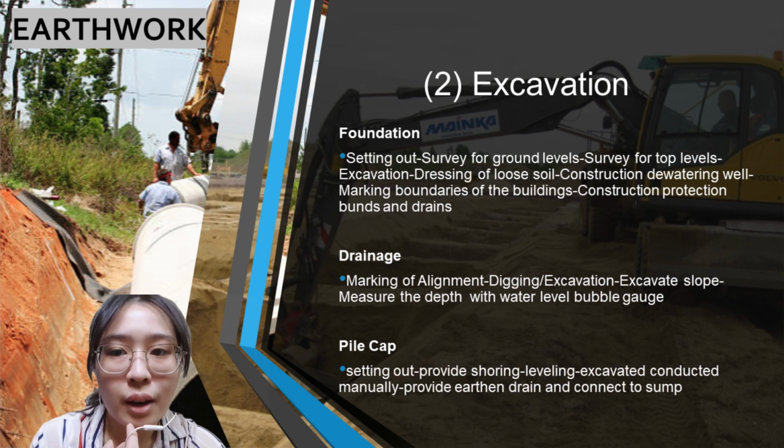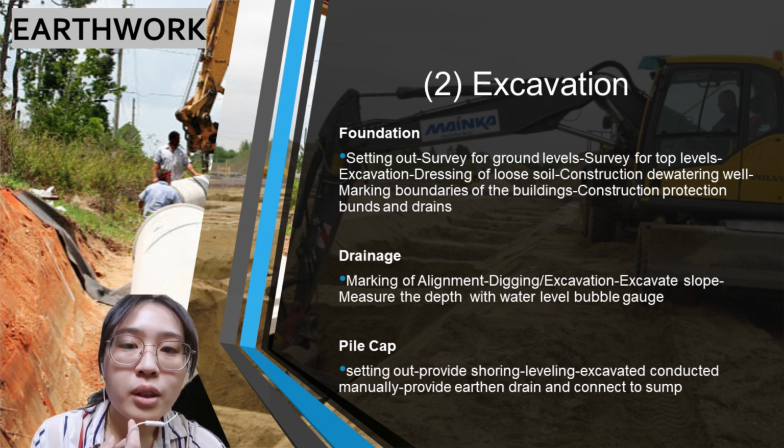We will first mark the alignment tool. Then we will go for the digging and excavation. Then we will excavate the slope for the safety of the workers. At last, we will measure the depth with a water level bubble gauge.